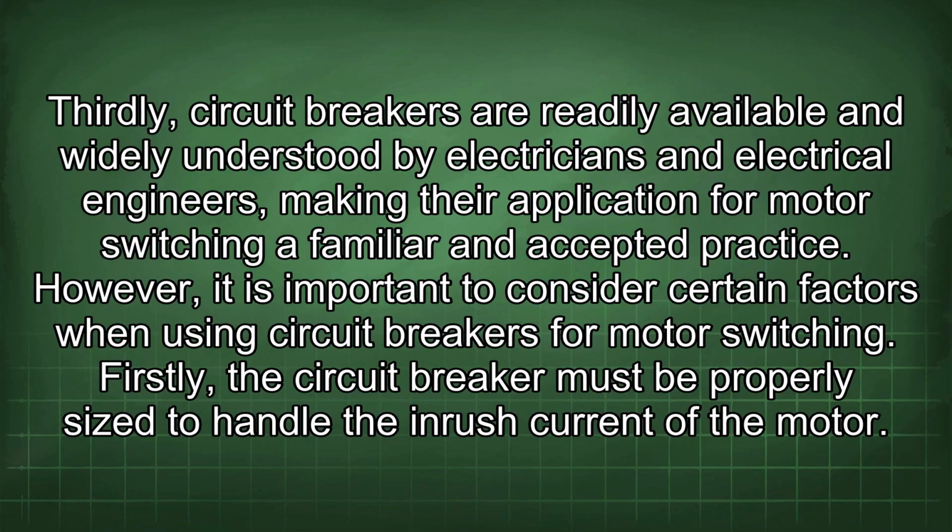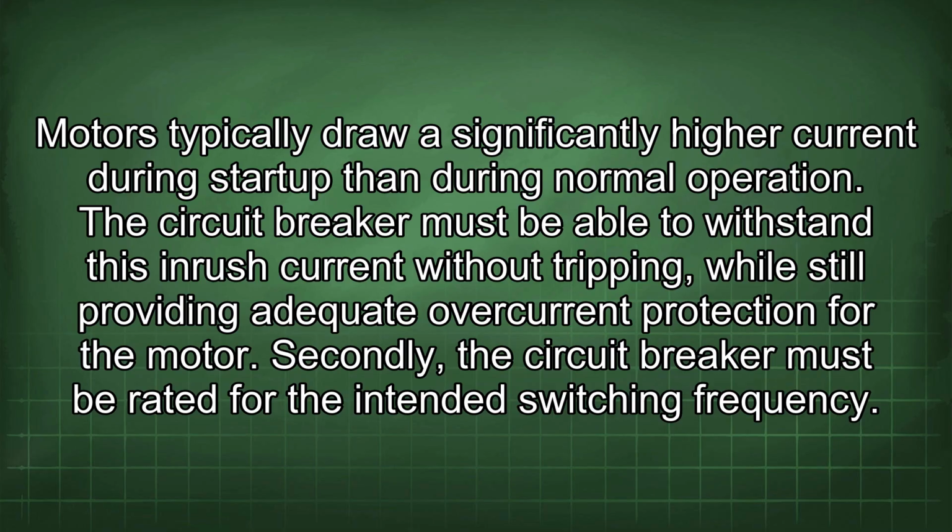However, it is important to consider certain factors when using circuit breakers for motor switching. Firstly, the circuit breaker must be properly sized to handle the inrush current of the motor. Motors typically draw significantly higher current during startup than during normal operation. The circuit breaker must be able to withstand this inrush current without tripping, while still providing adequate overcurrent protection for the motor.